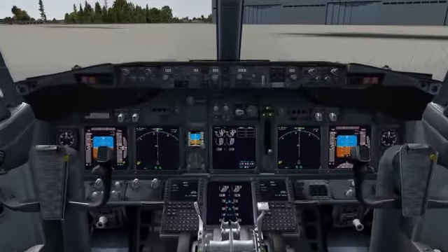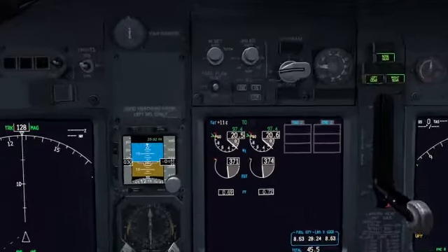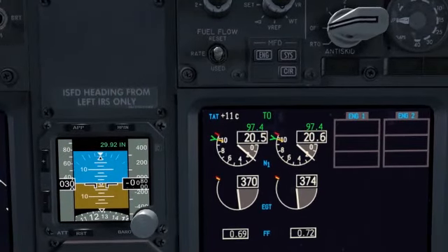The EEC uses analog and digital data to calculate the required engine fuel and controls output to operate the engine through the fuel supply that the HMU provides. The mass flow of fuel that goes from these components into the fuel nozzles in the engine is measured by a transmitter that provides fuel flow indication.